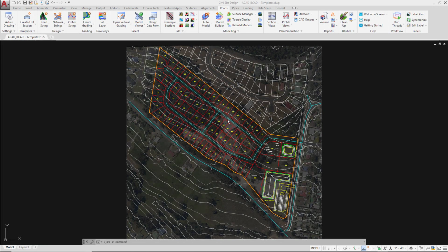When we created our base and grading string and our building pad grading string, we applied a template. Templates are great to enable us to show some kind of shape being applied onto the string for the purposes of a cross-section. In the grading string form, we actually access the template editor via a small pencil icon, whereas we can actually do it via the ribbon.